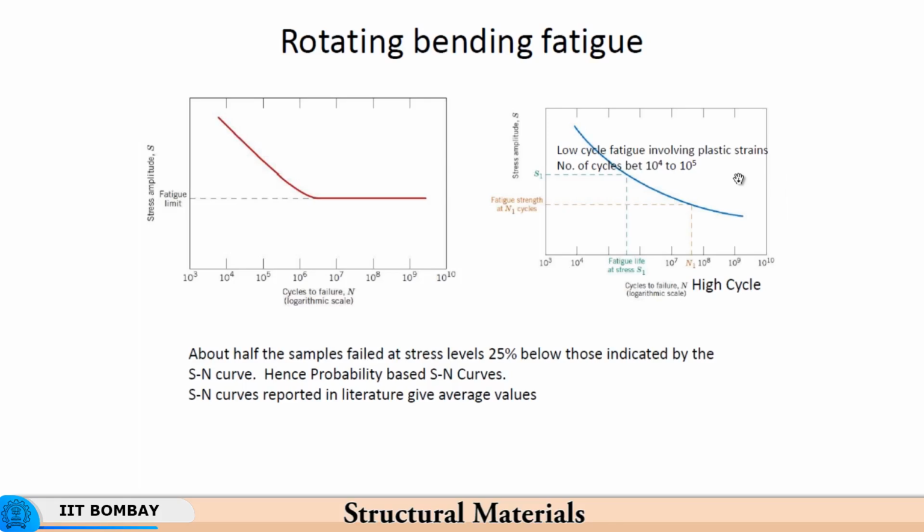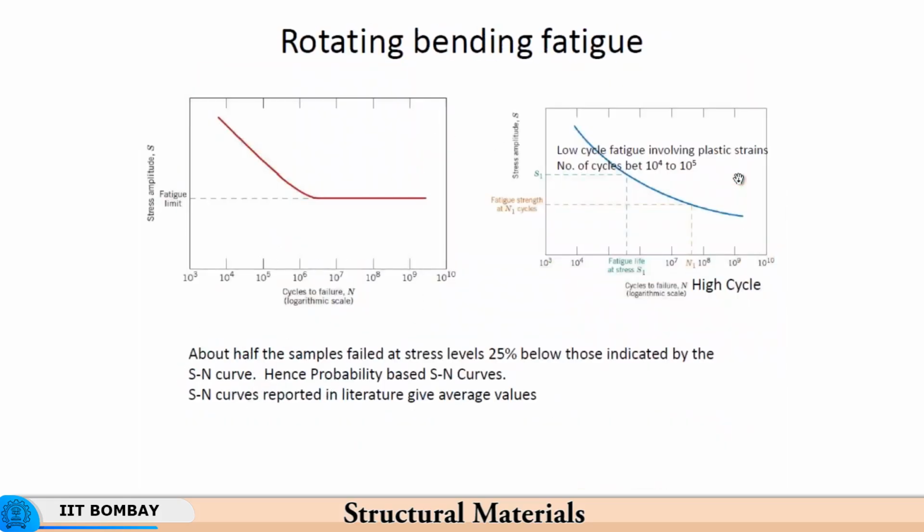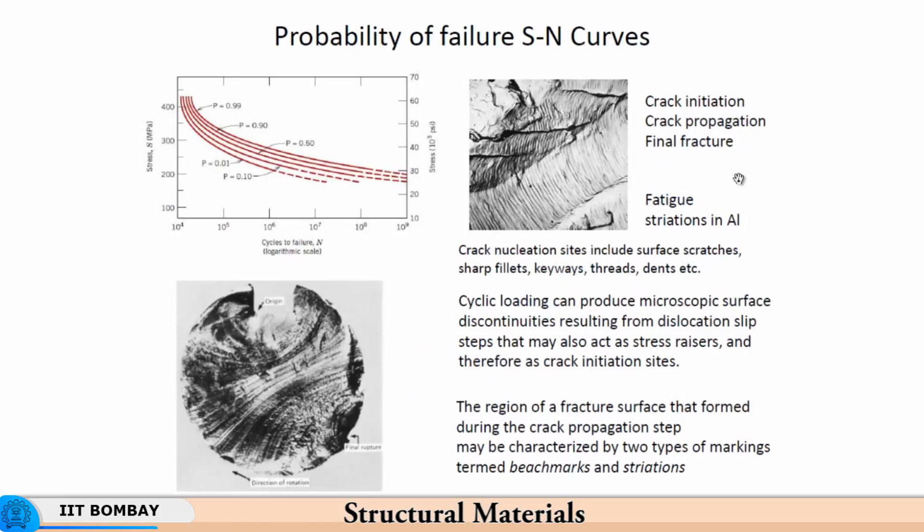So this so-called SN curve, that is the stress amplitude to cycles to failure curve, is used for designing shafts which will withstand a large number of cycles, particularly motor shafts which require a very high level of reliability. One has to be sure that they will serve for the entire lifetime, right. That is the reason why this SN curve is always consulted when one designs shafts for fatigue damage.